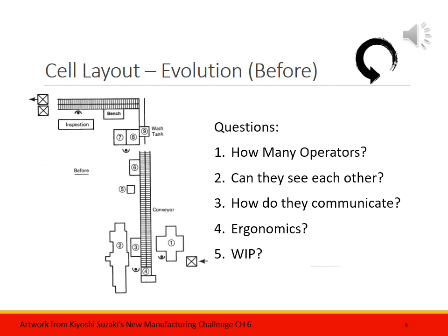Now maybe because operation 6 sitting there is a machine that runs wickedly fast but has lots of downtime. So what that would mean is you'd have to have a bunch of WIP ahead of it, so that when it's running, it can run like crazy and drain the line. And then when it has a problem, and the machine stops, and the andon light goes on, the guy standing right there at machine 6 goes over and clears out the nest. While he's clearing out the nest, the conveyor's filling up. Okay, that is one solution. It's not the best solution, but I have seen it work.